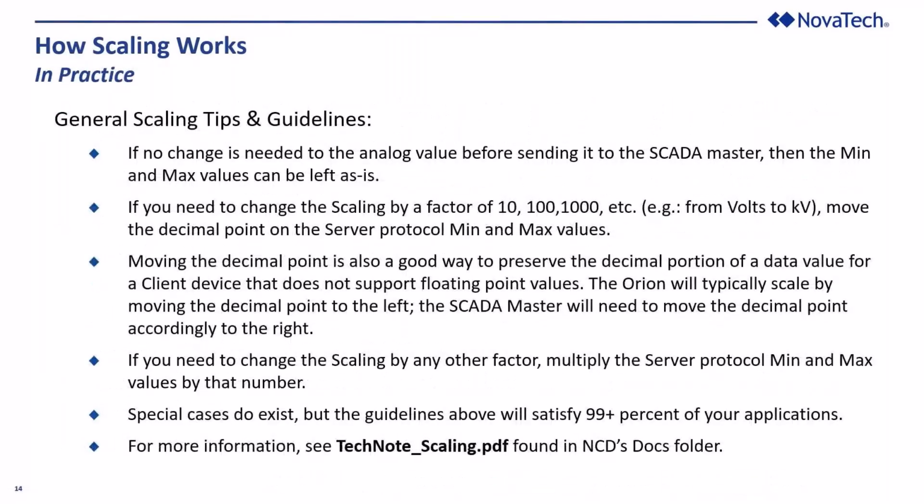So, in summary, some general scaling tips and guidelines. Again, if no change is needed, minimum and maximum values can be left as is. Changing from volts to kilovolts, again in the server port, if you move the decimal point either left or right, that's a really easy way to scale from volts to kilovolts or whatever decimal movement you need. It's also a good way to preserve the decimal portion of a data value.